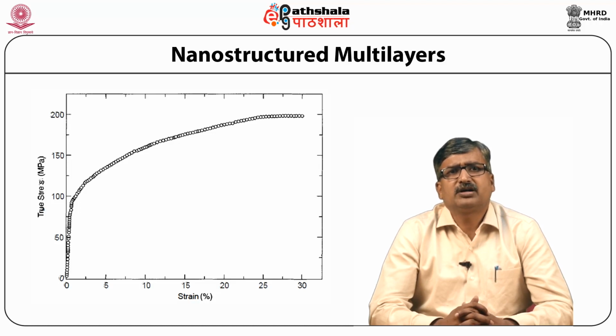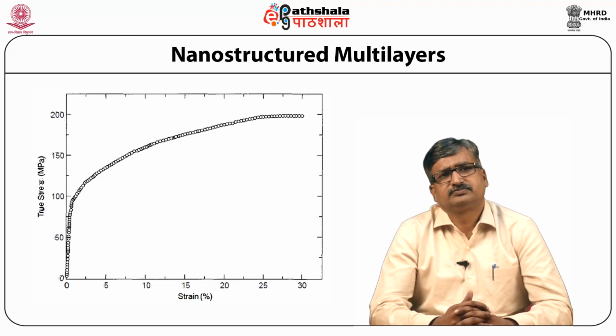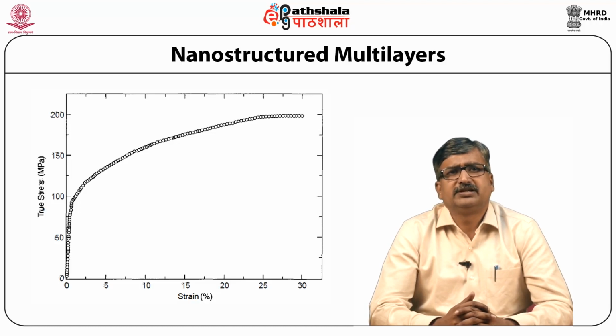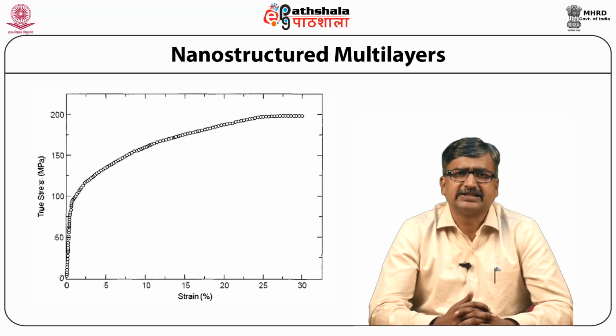The figure shows a plot of hardness of TiN/NbN nano multilayered structure as a function of bilayer period, or thickness of the layers, showing that as the layer gets thinner, in the nanometer range, there is a significant enhancement in the hardness until 30 nanometers, where it appears to level off and become constant. It has been found that mismatch of the crystal structure between the layers actually enhances the hardness.